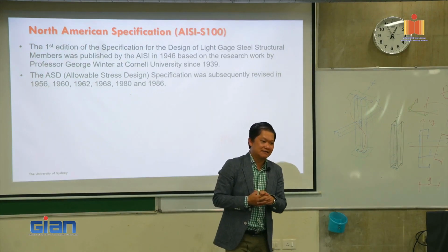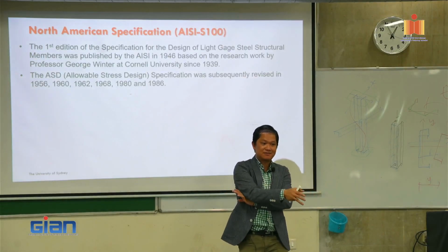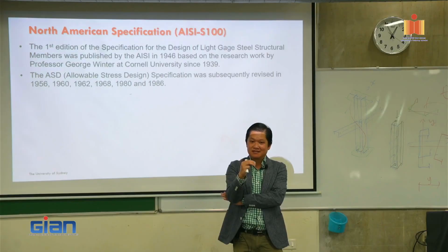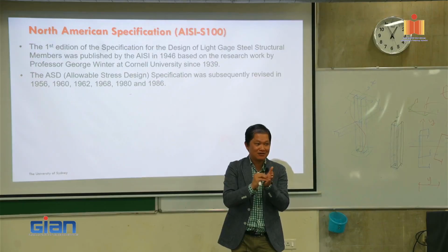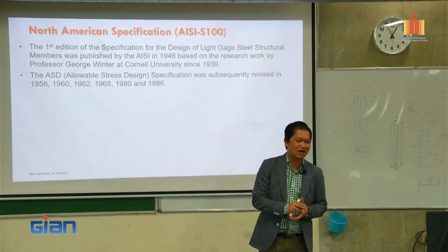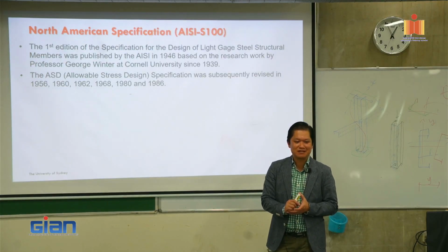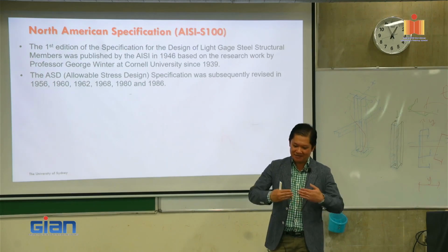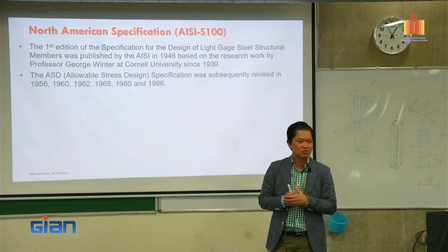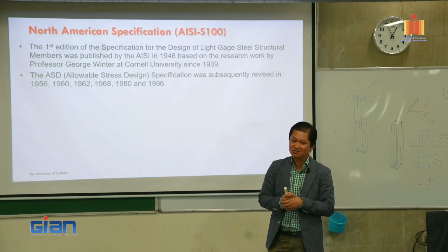And the second one is the strength as well. Because when it buckles, this side is different and that side is different, because the lip is going down and there is more compressive stress acting on that. So it's a lot more complicated. So we're trying to understand it and get some testing. We built a test rig to test channel sections and Z sections subject to flexural-torsional buckling at Sydney Uni, and we can see a lot of difference. So it's not just equivalent.